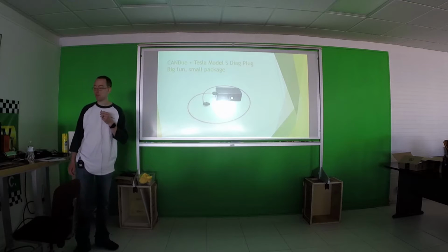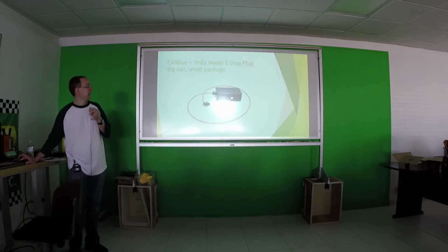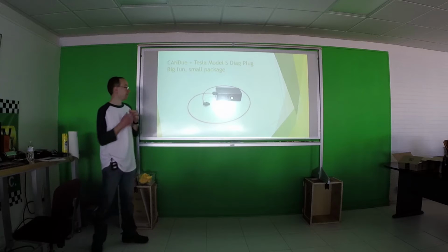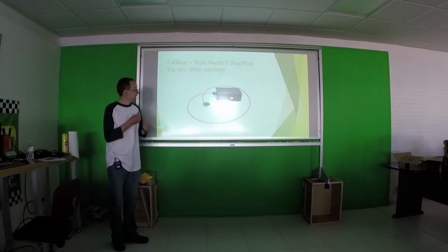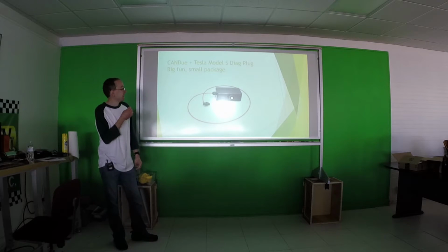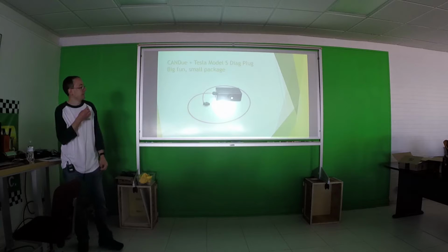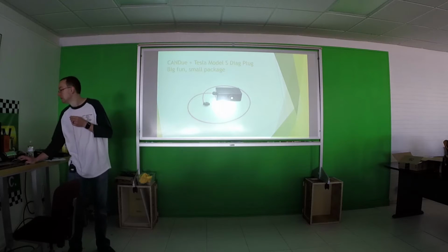Some of the hacking attempts that people have done in the past, they've tried to use Ethernet and some other diagnostics ports that Tesla was able to turn off. So the handy thing here is the diagnostics port under the center console. This is a direct connection to the CAN buses on the car. There is no real practical way that Tesla can disable that because it's hardwired right into the car.